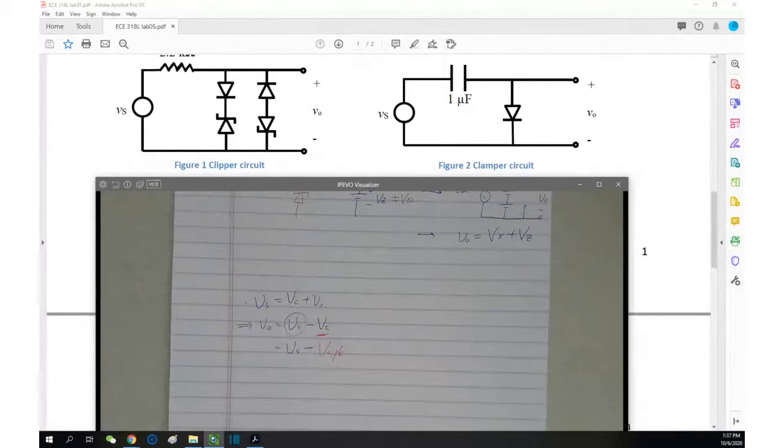Kevin, it's so long, I'm too tired to read this. Can you speak it? To charge a 12-volt DC battery with wall voltage, we would just have to add resistors between the Vs and the capacitor to bring the voltage peak down. Then you're adding a resistor. That's good, but a resistor's function is to limit the current. You need a diode.